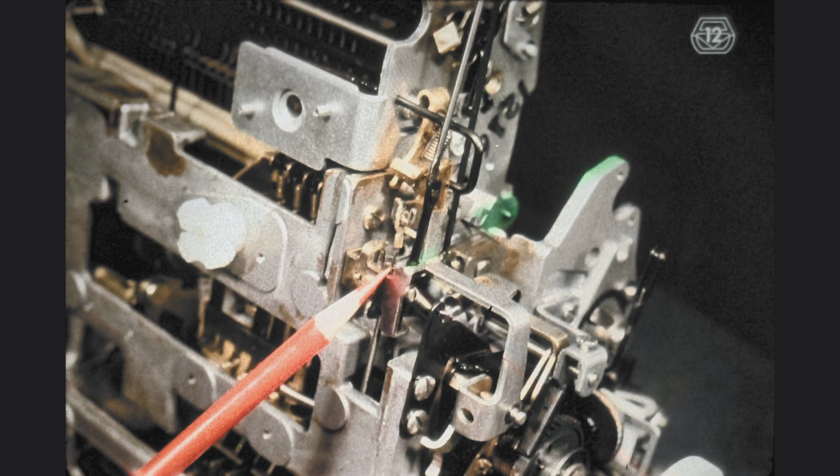To obtain the same condition on your machine, press a comma or a period, and then half-cycle your machine, which means turning the operational cycle shaft by 90 degrees, top to the front.